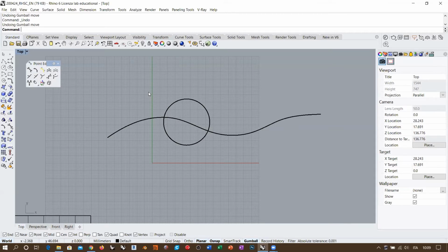Okay, so insert control point if you are working with a regular geometry, regular shapes, where it doesn't matter more or less if you have some deformation during the point insertion. But in general, I do recommend that you get used to working with knots, inserting knots. Okay, so remember that knots create spans, and spans are driven by a set of 4 control points in general. So once you define little spans here, you are also basically creating a dense population of control points in the correspondent area. And so you have local deformability, right?